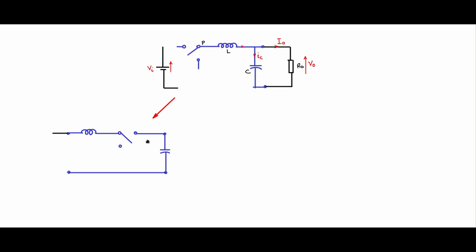Capacitor is connected to the output, and to the input we have the unregulated DC input voltage, and to the output you connect the load like this and complete this single pole double throw switch connection. Now this is a single pole double throw switch, L. This is a pole, this throw 1, throw 2, C, Vi, R0, V0 measured in this fashion, Vi measured in this fashion. This is IL. Now such a converter where the inductor is on the input side and the single pole double throw switch is configured in this fashion